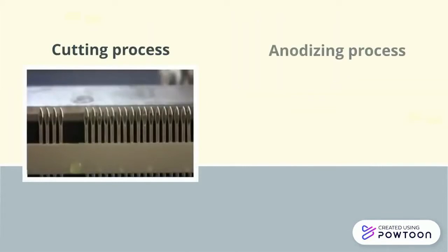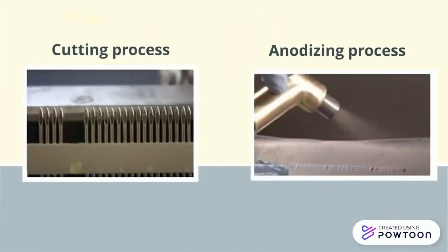Cutting process. Grinding cutting is the removal of metal by the use of abrasives joined together to create a revolving wheel. When the moving abrasive particles contact the workpiece, they operate as small cutting tools, with each particle removing a tiny chip. This process operates when a tube moves across a grinding wheel to grind and sharpen the tops of the tube into a finer point and shaping it into a rough point.